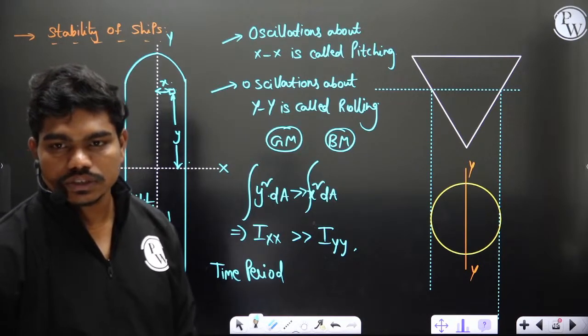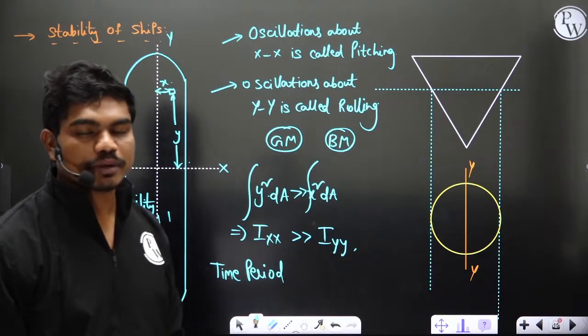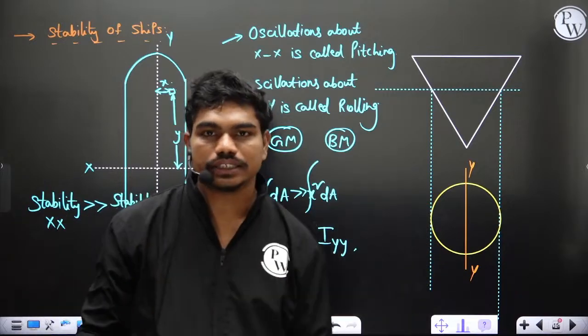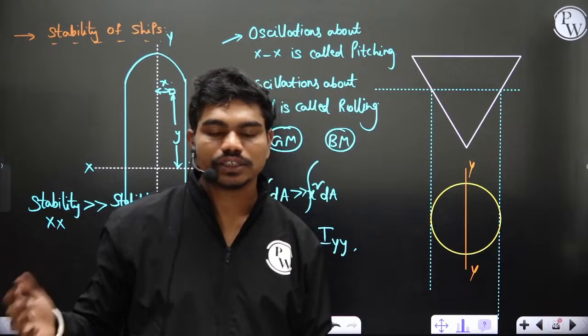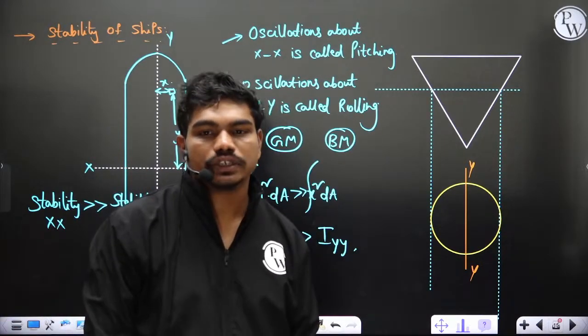While in a cyclone, speed is reduced to 5 knots from 30 to 34 knots. Yes, generally velocity is reduced because it's like the impact of two high-moving bodies. Wave and ship both moving at high velocities, then definitely the effect will be large. So you cannot control the wave velocity, so better you bring down the ship velocity. That's what we do.